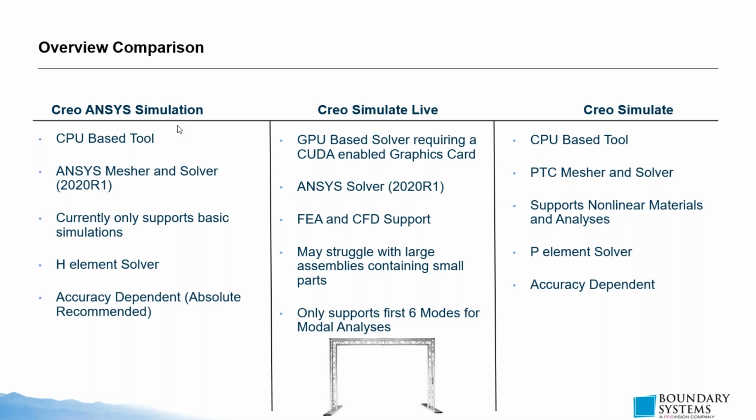However, if you're looking at the nonlinear aspects, where plastics start to behave nonlinearly or in the thermoplastic region, neither Creo ANSYS Simulation nor Creo Simulate Live would be helpful in that regard. But Creo Simulate is poised to handle plastic materials the best. The tools on the left can only handle the linear region aspects of plastics.